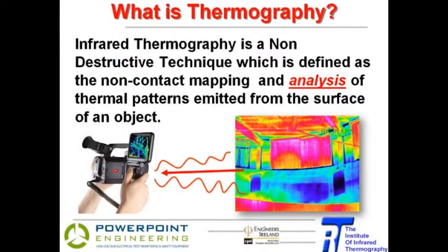People very often, when you turn up with an infrared camera looking for an underfloor heating leak, say, how far down into the ground will the camera see? Well, the answer is it doesn't. It's only seeing the first surface molecular layer of most materials. But because of the nature of heat transfer, we can find a heating pipework leak because of that energy being conducted through to the surface.